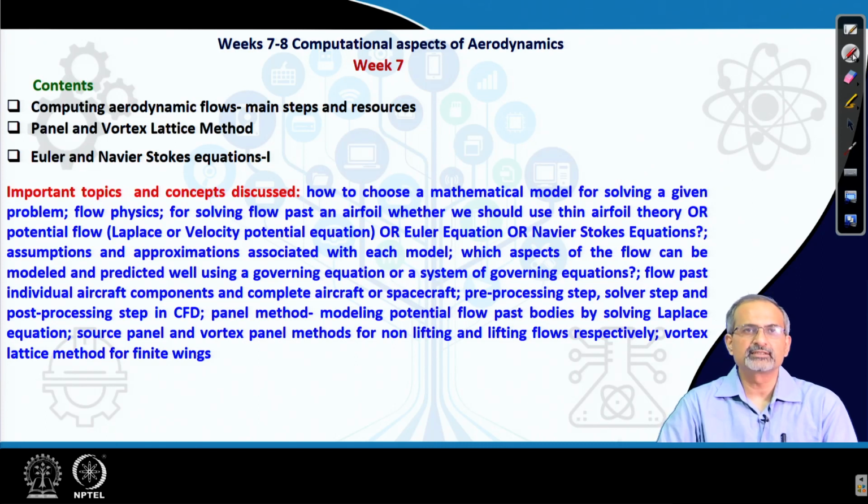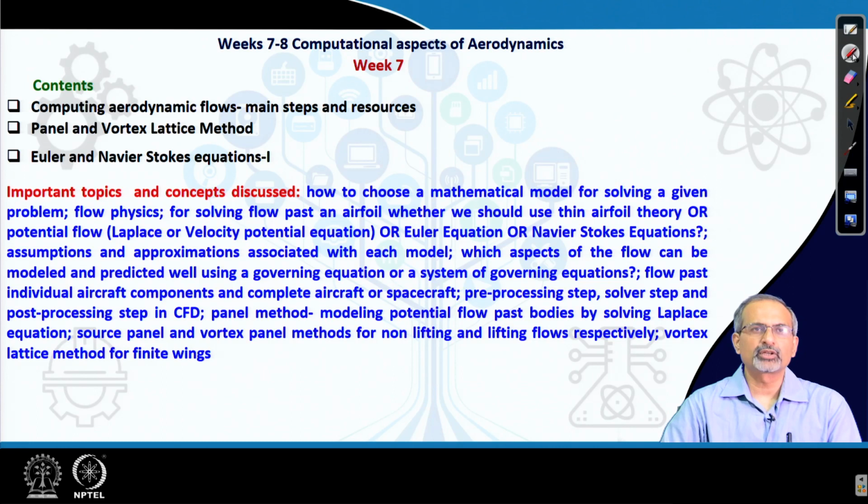and post-processing step. And then towards the end of the week, we discussed the panel method, which is a tool to model potential flow past bodies, and where we essentially solve the Laplace equation using a numerical scheme. Both source panel and vortex panel methods were discussed, which apply to non-lifting and lifting flows respectively. And finally, we discussed the vortex lattice method, which is applicable to finite wings.